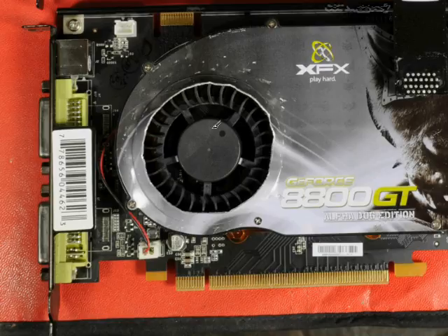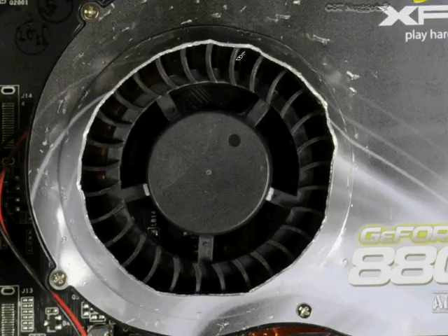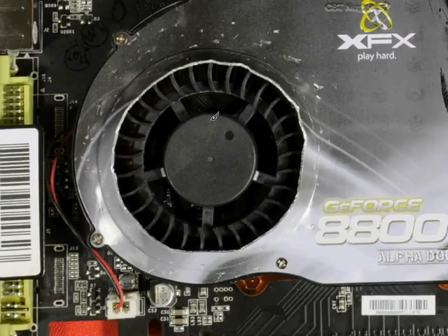And if we take a closer look, you'll see that I had to pry up this metal around the fan housing. And apparently they had spec'd this too tight, and the metal and the fan were rubbing against each other, and it had seized up this fan. Apparently it burnt out the video adapter or something like that, so I wasn't getting anything out of it. I don't know how long it had been like that, but anyway, that's just something else to keep in mind and to look out for.